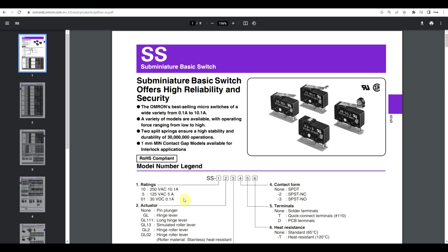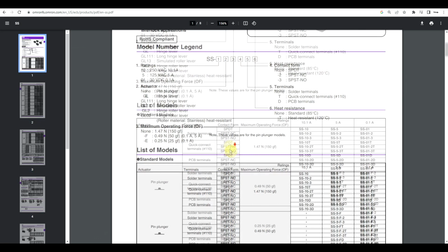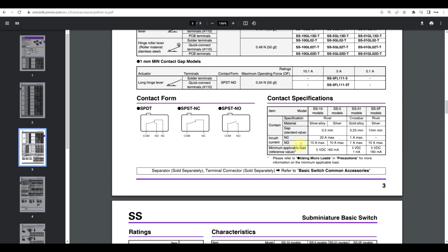By exceeding these a little, the switch's lifespan will usually be reduced, and by exceeding these parameters a lot, the switch can be completely broken the first time. A really good datasheet will also tell you that the switch can handle slightly higher values of current for short periods of time, so during inrush events.